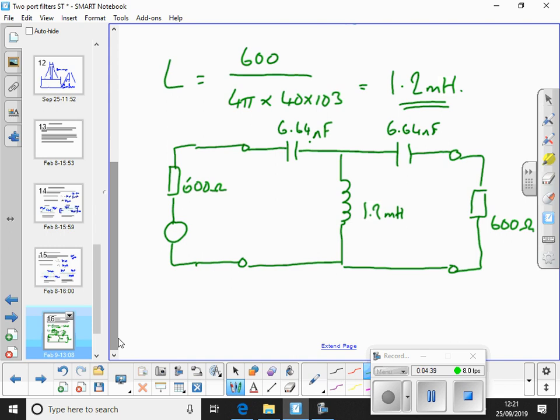Yeah. So the idea of this is that you then put that in LC, and you can simulate what happens when you change those components to the preferred values, and that's going to shift your cut-off frequency slightly either side of where you designed it to be, slightly either side of 20. Yep. Some of the examples that I give you are close. Some of them are that much further away.